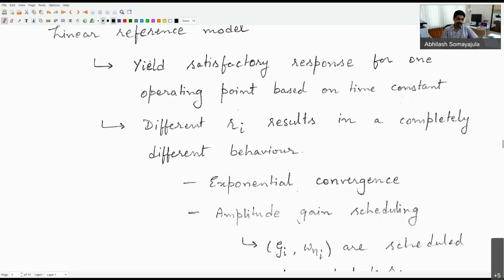So for example, let us say it is asking me to generate a surge velocity, let's say for my scale model, of 5 meters per second. Okay, and the power required for that is, let's say, 1000 watts. I need a 1000-watt motor. But what I have on board is a 400-watt motor, then I will never be able to generate that speed, or the acceleration required to generate that much thrust to reach it. Even though my guidance system may say your desired value of velocity is 5 meters per second, I may never be able to actually get there because I don't have sufficient power.